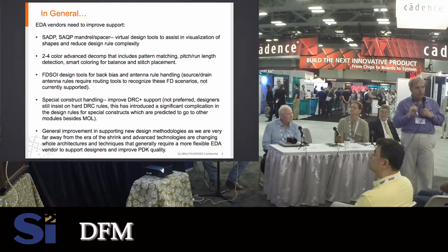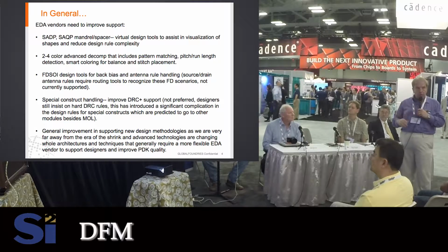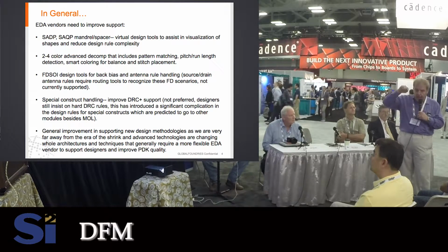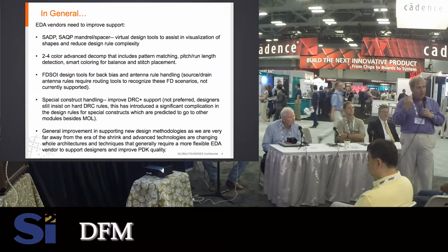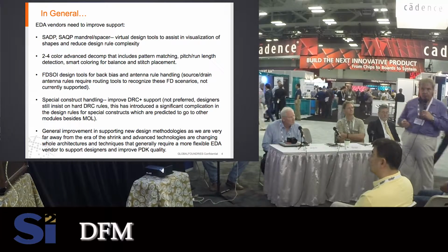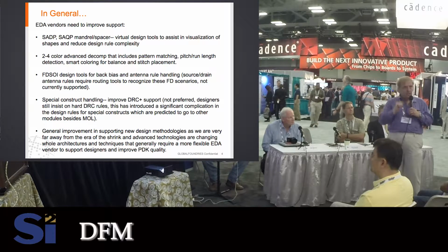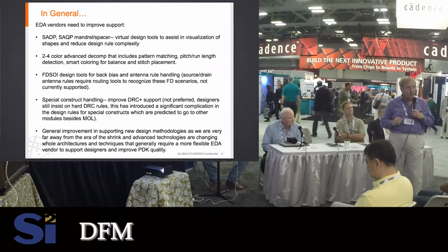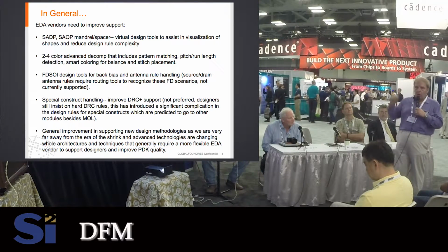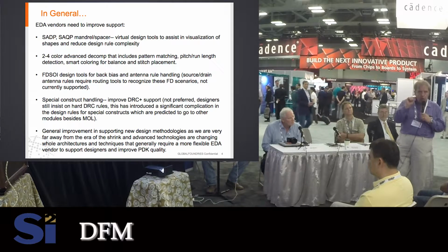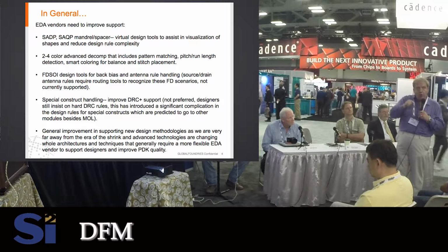You're going to start seeing 10 nanometers, 14 nanometers, and below, features that appear on silicon that are not drawn. You have cut layers, like Dr. Raul showed. You have mandrels, because drawing the edges of your back end is more important than the actual circuit or the metal. So you have features there that you can have spacing violations, width violations, and min area violations on, that you're not drawing.